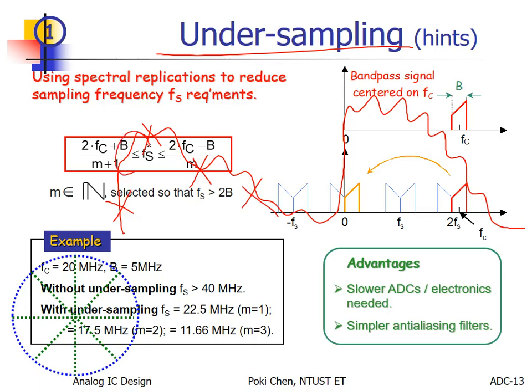You will miss some of the detail of your input waveform. You say, hey, I would like the first sample here, the next sample there. Oh, congratulations, you will get a better view of your signal, right? But it is even harder for you to tune the oscilloscope. Anyway, nothing is free.